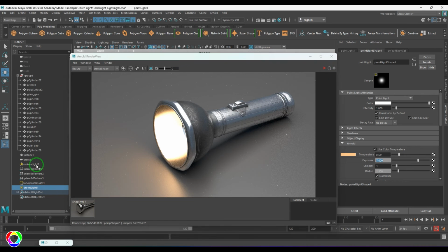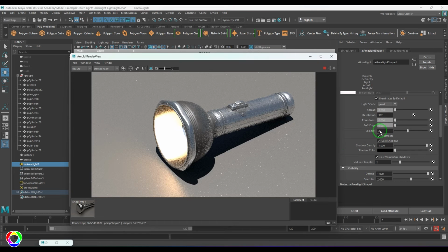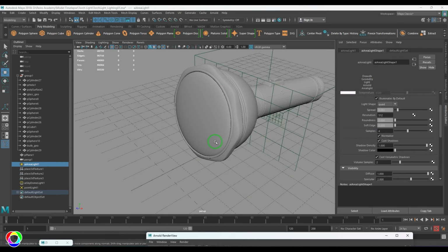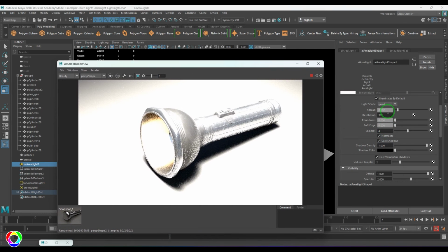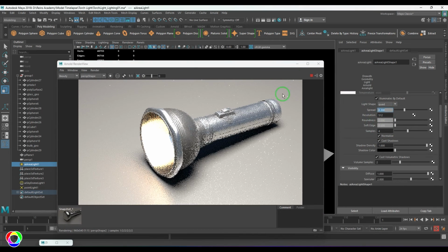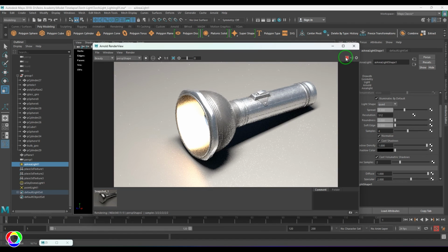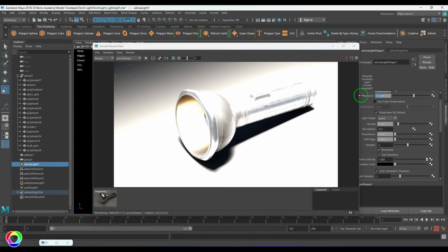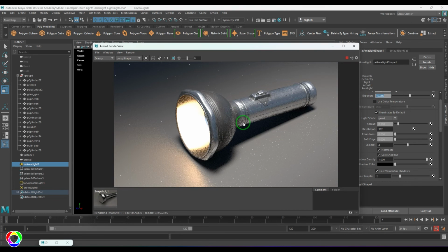I'll also just explore the light from the top. We have the light spread value. I'll reduce it to 0, and I will slightly increase the spread. Let me give that effect of spotlight. So I'm going to scale this, and spread value is 0.3. I'll scale this light. Exposure, let it be 8 there. 8 or 9, 10. Okay, this is giving me that radiation and some light.